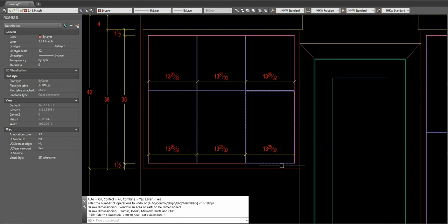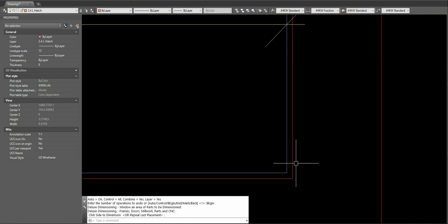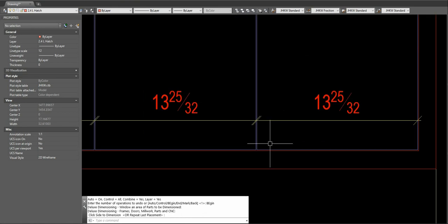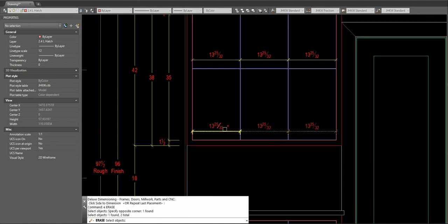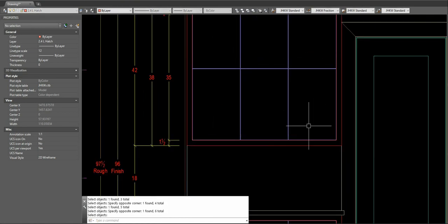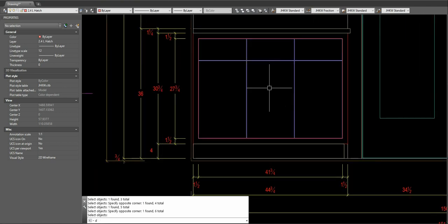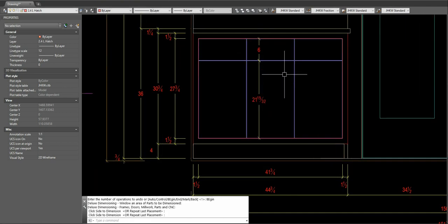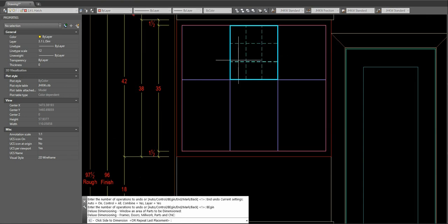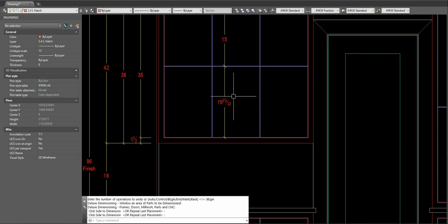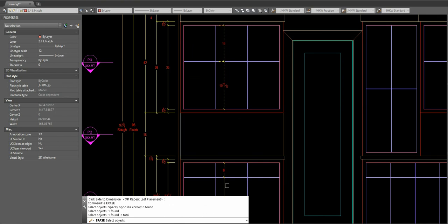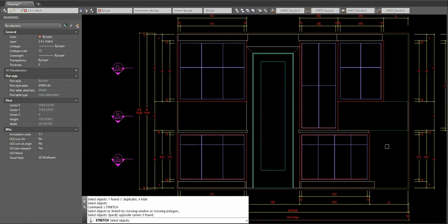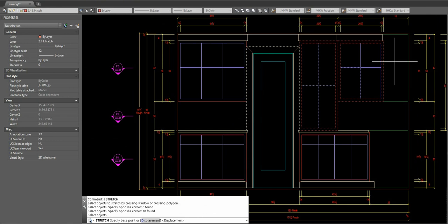They are all equal width and they all have a margin that I've defined. At some point it defaults to 3/32, but whatever you want for a margin, you can do that. And same with the height. I've got it defaulting to 6 inches for a base and 15 for an upper, but these are just rectangles, so you can stretch these as your heart sees fit.